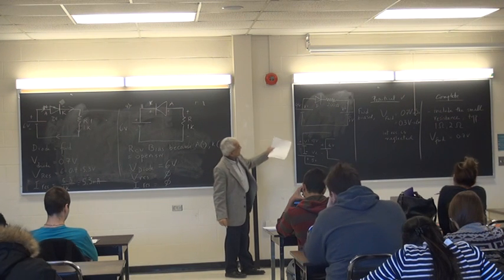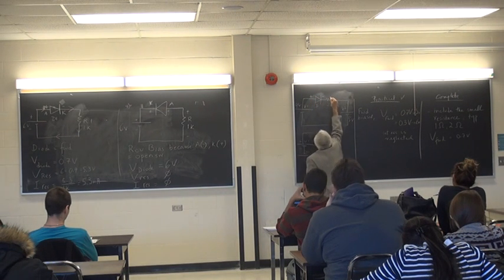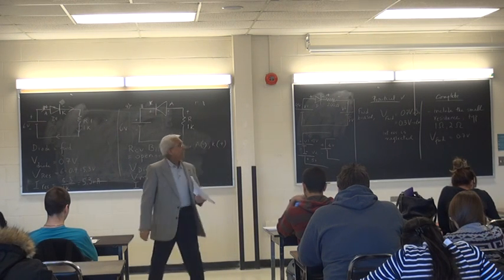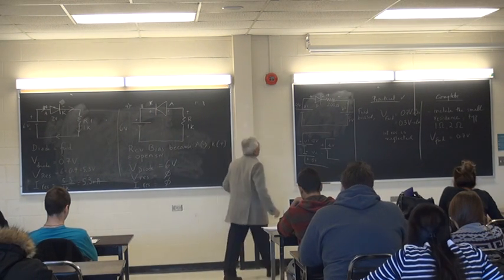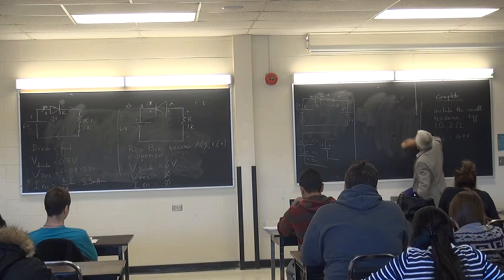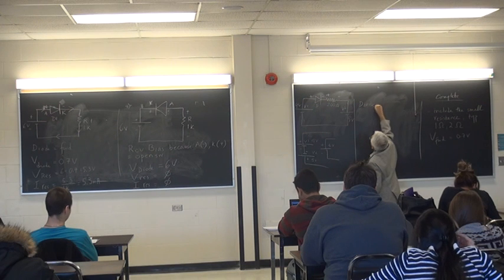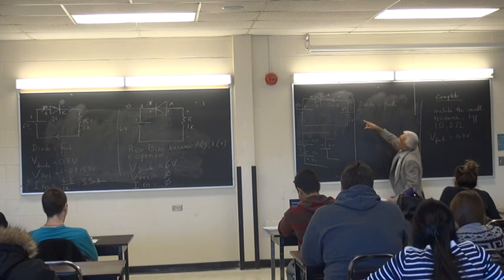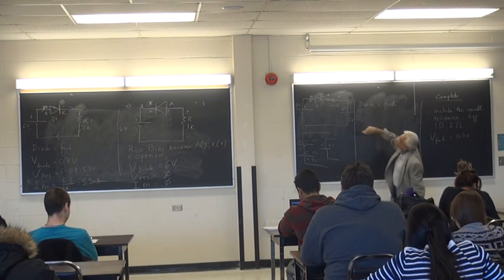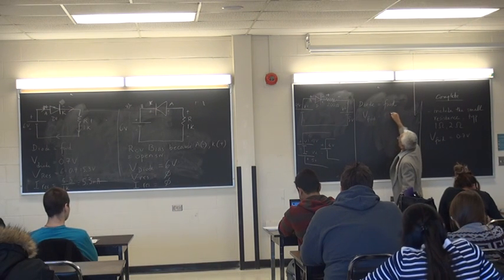So with the 4 volts, that plus minus will result in plus minus and plus minus, which means that the diode is forward biased or reverse biased? Forward biased. Because I can see that the anode side is positive, cathode side is negative, so it's forward biased, therefore V forward at the diode is 0.7.